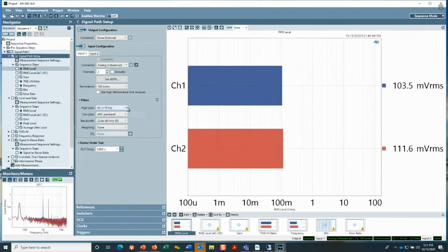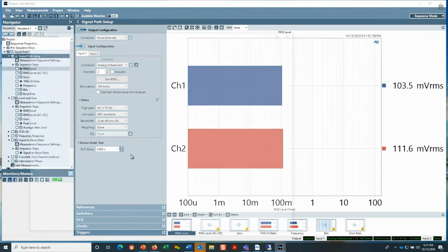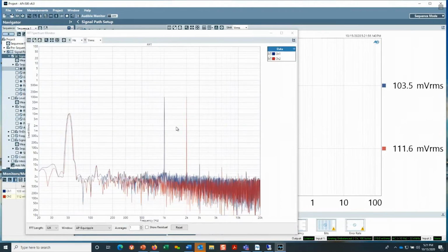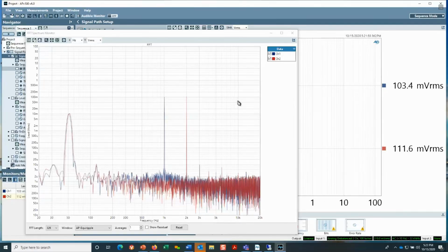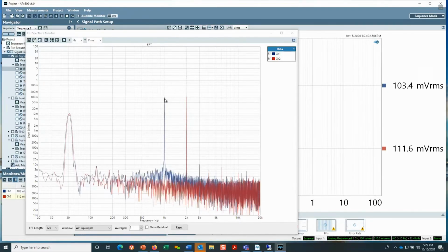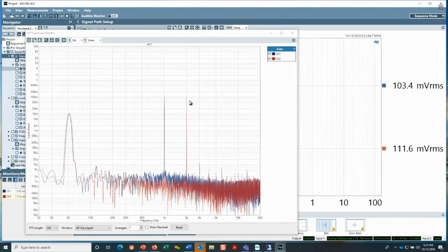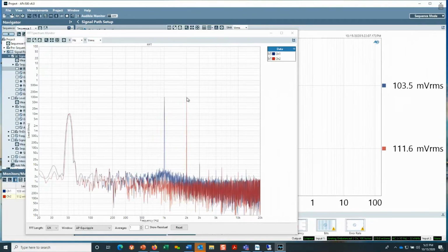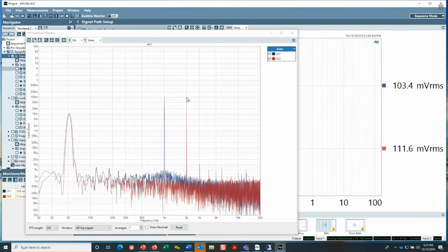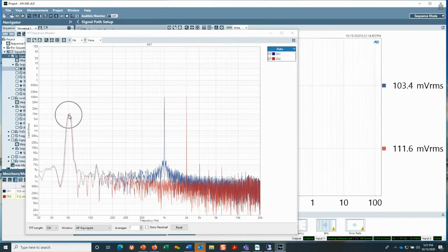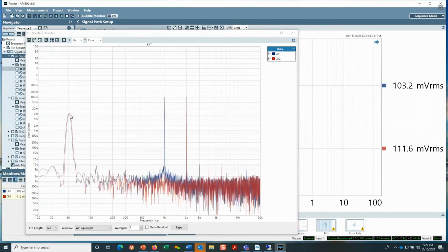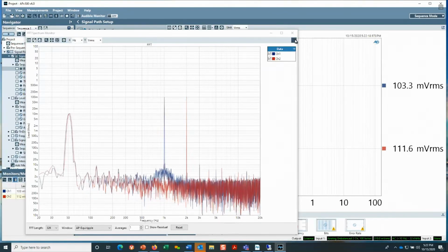And as you can see, let's turn down the volume so that's not so annoying. What I wanted to show you here is a special signal that we can use for that waveform verification step, or channel verification, to make sure we have the right connections. So this signal has a 1 kilohertz tone in channel 1, the blue trace, and a 2 kilohertz tone in channel 2. And if you're testing a low frequency effects device like a subwoofer, we have frequencies of 51 hertz in channel 1 and 52 hertz in channel 2. So it's kind of a useful signal for that.